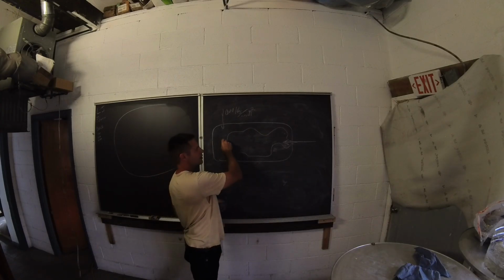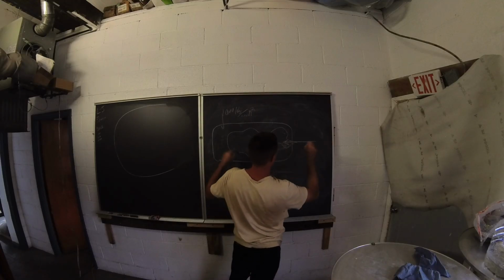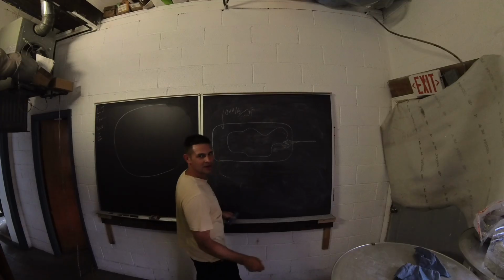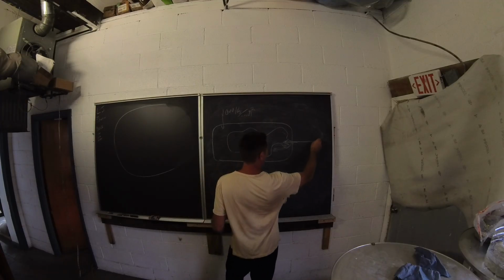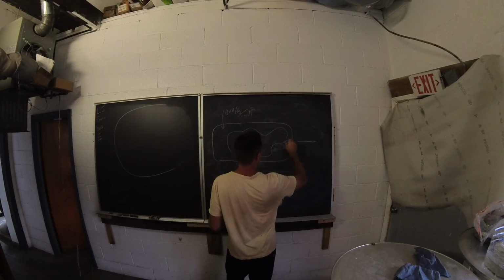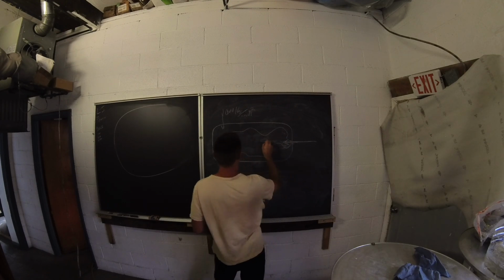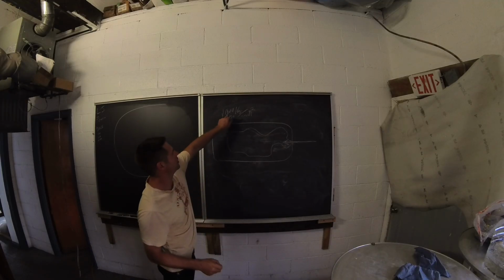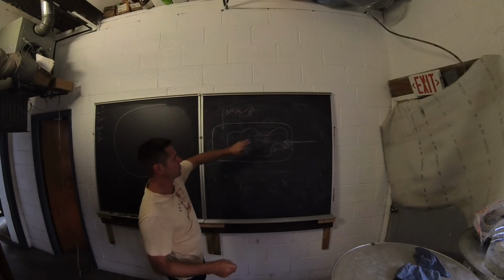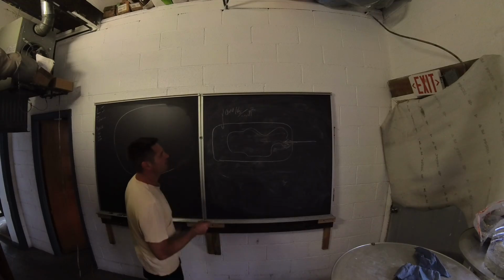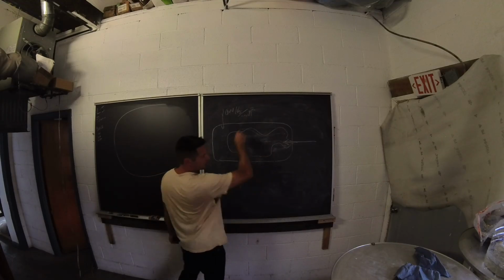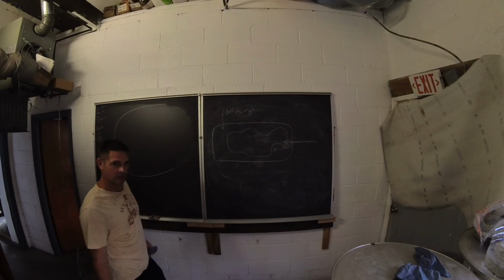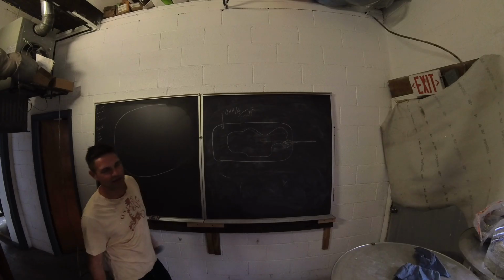So when you let it go to rest, the bag compresses and all the hydraulic fluid is pumped out. But get a hydraulic pump running, and it's going to pump hydraulic fluid in there and fill this whole mass, and at a certain point it'll raise the pressure in the tank commensurate with the volume. You wind up with a good volume of hydraulic fluid at pressure, and essentially it's a very useful bomb.